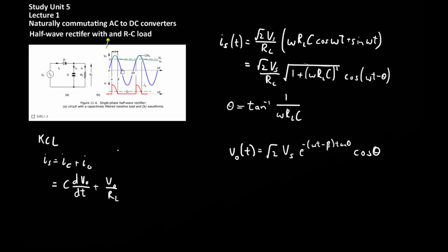The circuits covered in this lecture focused on half-wave rectifiers where there was only partial conduction during the AC cycle. So coming back to this example with the RC load, there is only conduction for a small part of the total cycle, where the converter network provides energy for the rest of the cycle. The remaining lectures will primarily look at full wave rectifiers for both single and three-phase voltage sources.